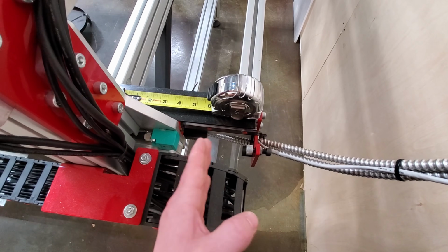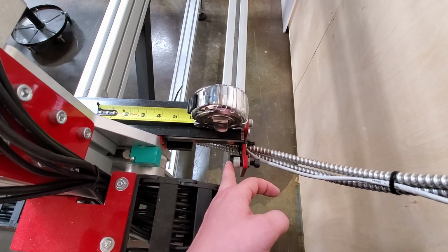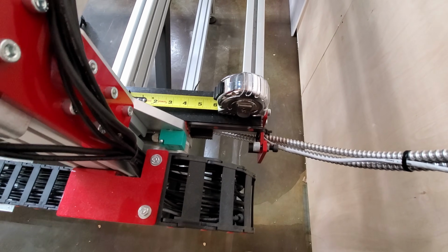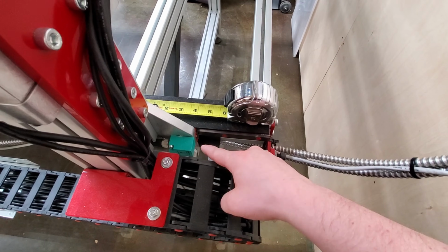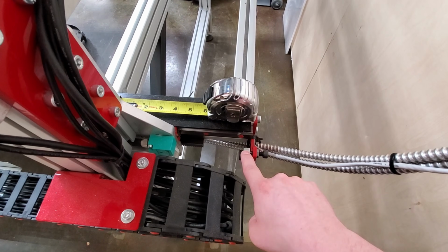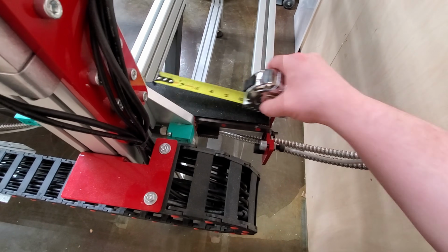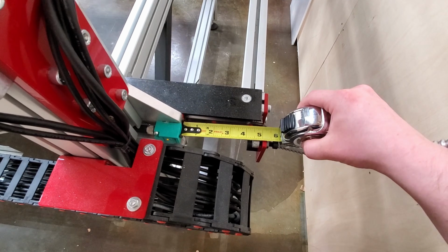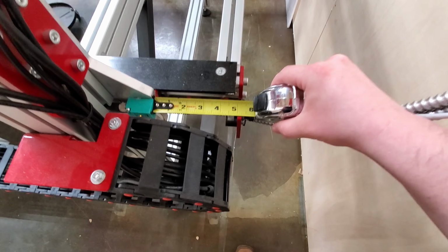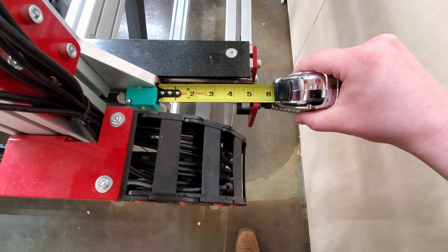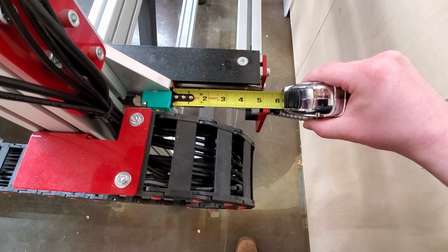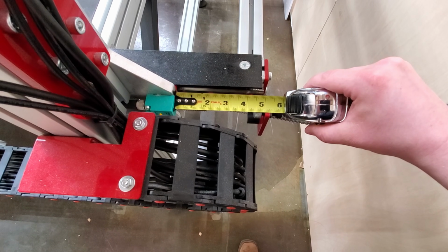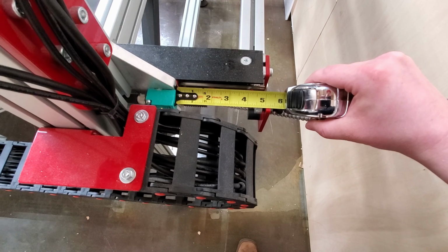Now, how much more space? Do you want to really squeeze it and risk running into this? I don't, so I just want to get really close. Remember, there was a 1/4 inch gap when the limit switches are fully activated by this piece of metal. So if I put a tape measure right here, I'm at right about 4.5, a little bit less than that. So what if I just go ahead and add 4 inches to that 120 value, change that to 124?